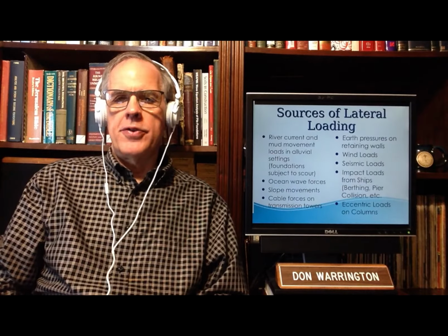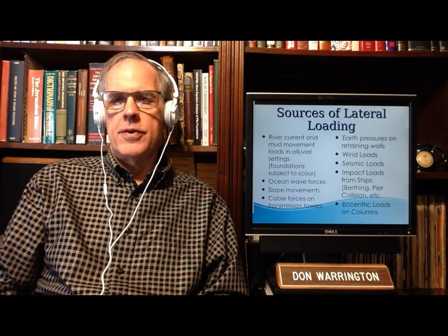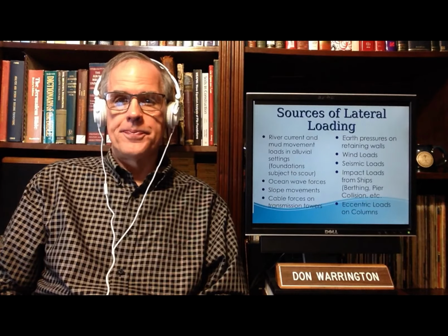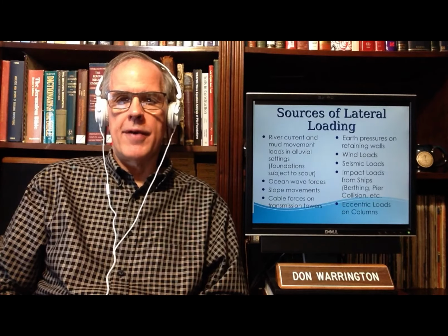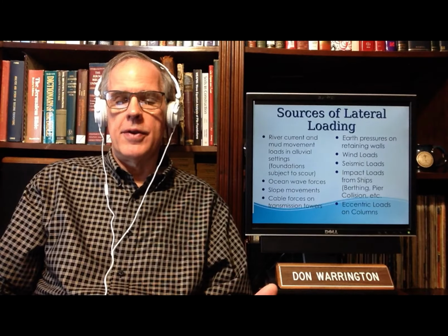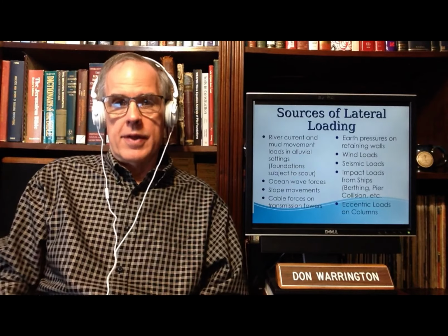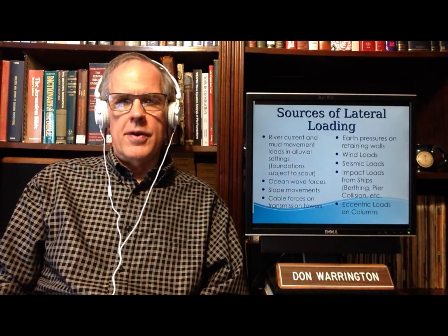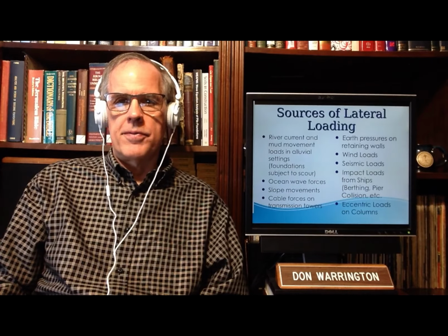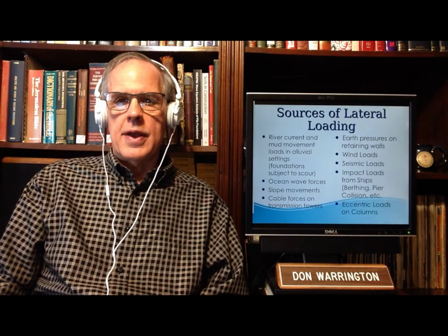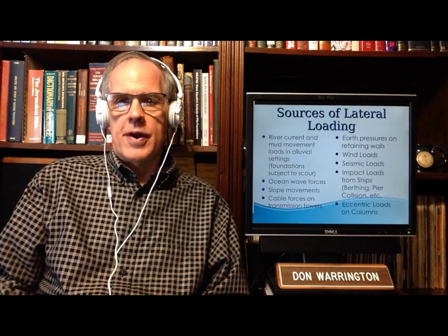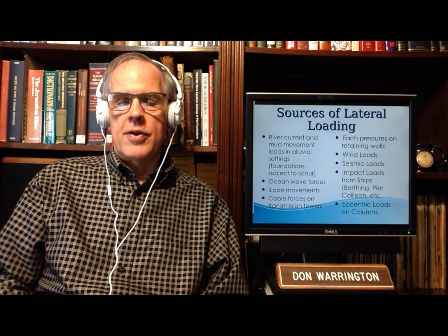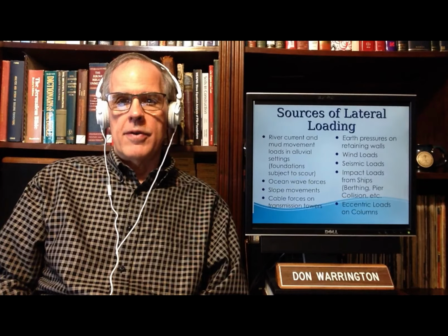In the very early stages of deep foundations, we talked about driven piles, and why we have driven piles to start with. A major reason why we have any deep foundation, whether driven piles or whatever, is lateral loading. Lateral loading, as we have seen, is not, generally speaking, the forte of shallow foundations. There are ways in which we can assist shallow foundations in withstanding lateral loading, but ultimately, if lateral loading is serious enough, we require a deep foundation.